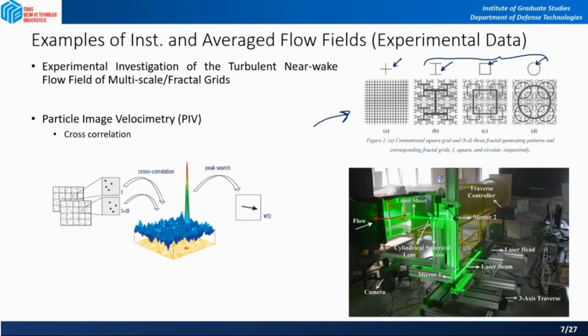What you see in this picture is a sample of PIV, particle image velocimetry, configuration that was set up during the study. You can see that there is a laser and all of these mirrors being used in here. We have some lenses to convert the beam of the laser into a sheet of laser. This is a laser sheet in here. And then there is a wind tunnel.